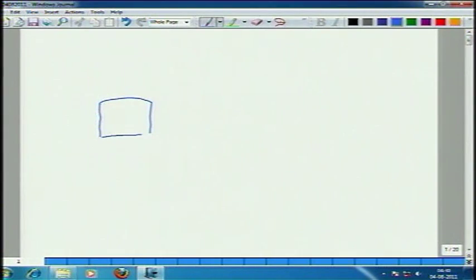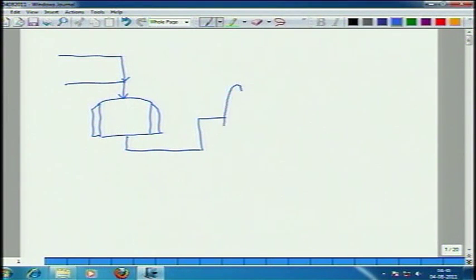So, welcome to this next class. I think last time we were looking at that same thing, A plus B goes to C, it's just that C is intermediate boiling, and so you had to have two distillation columns to do the separation. And we did a light out first train, which means that the lightest component is separated out first. Why did we do that?